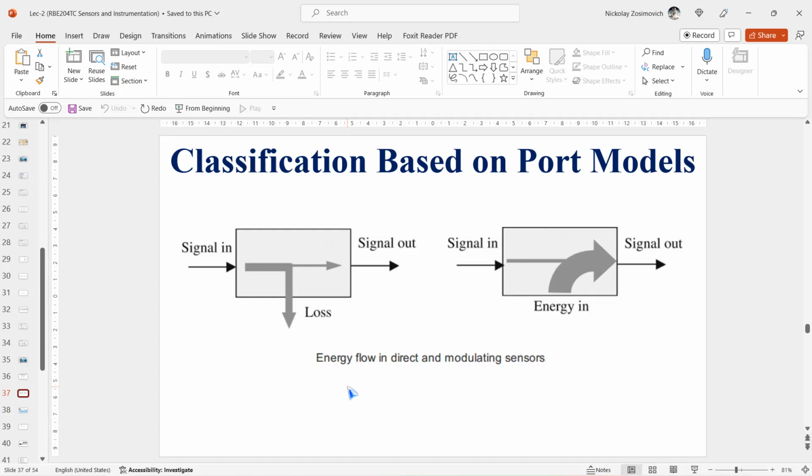An important advantage of a direct sensor is its freedom from offset. What does it mean? It means that at zero input, the output is essentially zero, right? Examples of direct sensors are the piezoelectric acceleration sensor and the thermocouple.